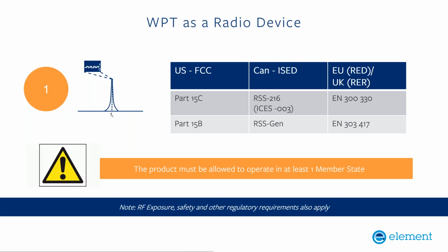But the reality is that all of these devices will also have to undergo an RF exposure assessment, which is a type of safety test, if you like, to make sure that we as individuals and domestic animals are not exposed to RF levels and fields which would give us a degradation in health. And so whilst in theory there could be infinite power transmitted, it's the RF exposure requirements that will really define what powers can be used in WPT applications.